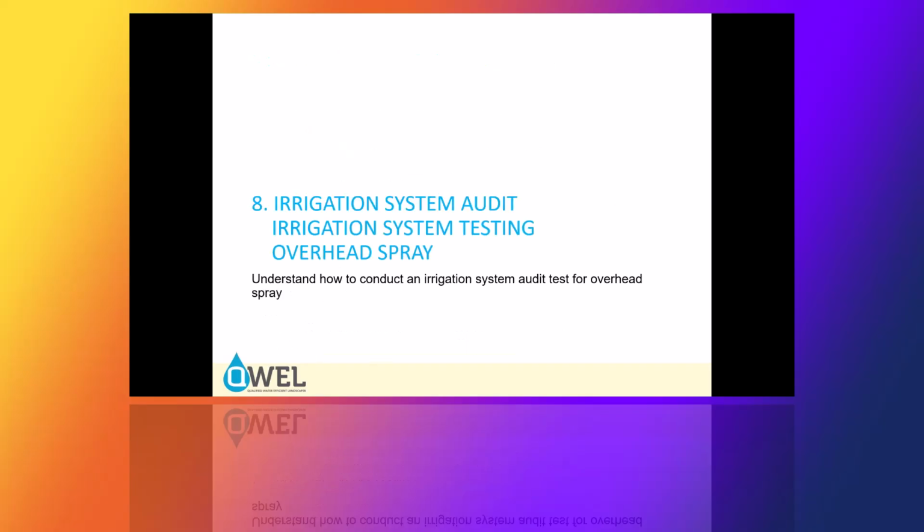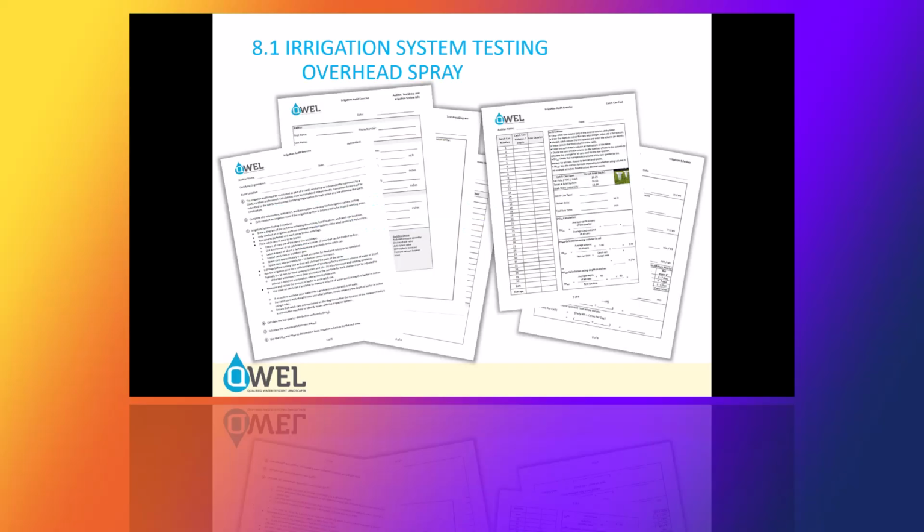Irrigation system audit, irrigation system testing, and overspray. So we want to understand how to conduct an irrigation system audit test for overhead sprays. These are some of the forms that we're going to be working with. It's a copy of the QWEL Irrigation Audit Exercise form. I really like how they set up these forms because it walks through the formulas step by step, including the scheduling. It's a great form and it's an easy way to understand what you're doing.